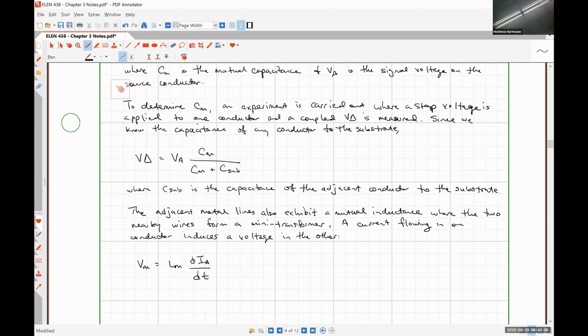So that's part of the reason why the design rules say the spacing between metal conductors of different potentials has to be a particular value, but the more space that you can put between your conductors, the smaller amount of problems you're going to have with crosstalk and signals bouncing around inside your system and making things behave like they are not supposed to.